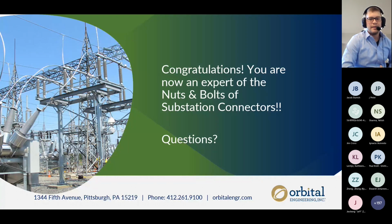So between doing your bus calculations and looking at what your limiting factor is for different connectors, you want to make sure you are not the limiting factor. The way I always try to look at it is you don't want that to be your weakest link.